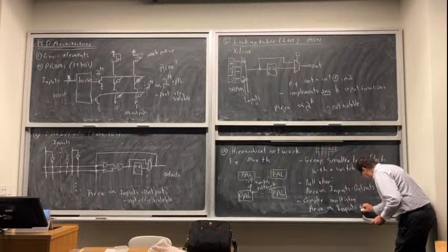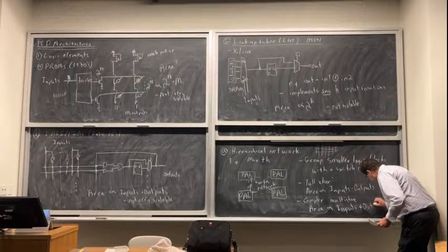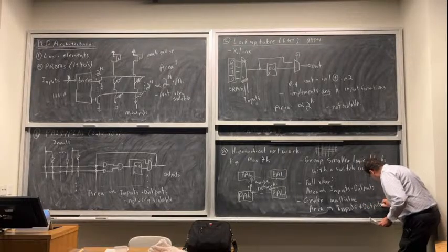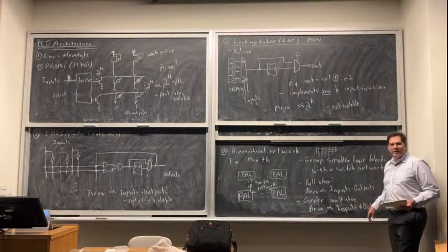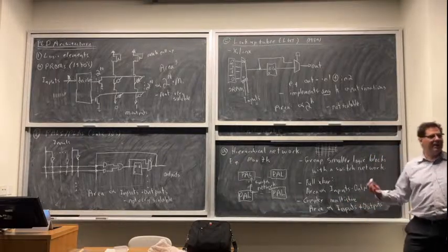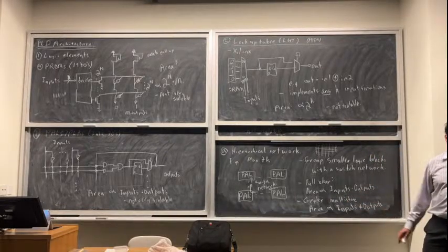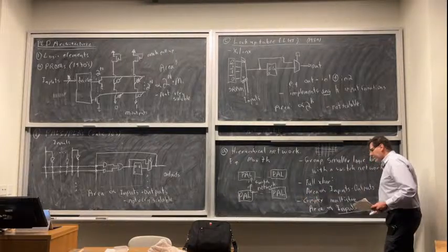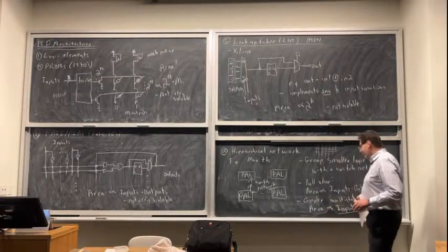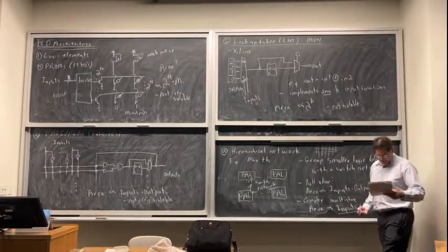Okay, and this is a big part of making a good FPGA architecture: exactly what does that mean, right? There are a lot of different ways you can make some complicated multi-stage routing network. If you do it well, the area is pretty good and it doesn't block that often, meaning you don't get routing failures very often. If you do it poorly, the area is big and you get lots of routing failures.